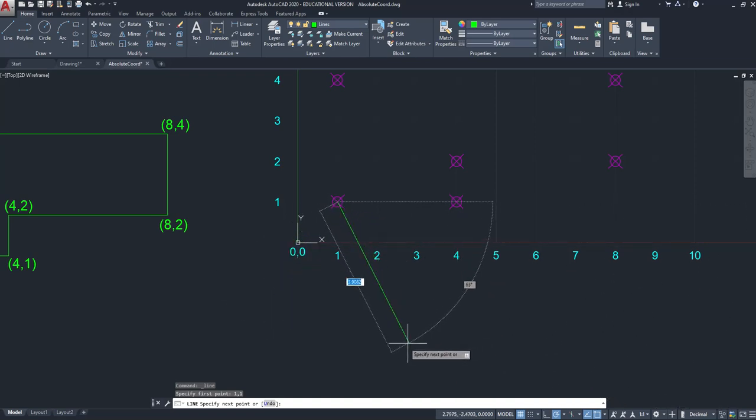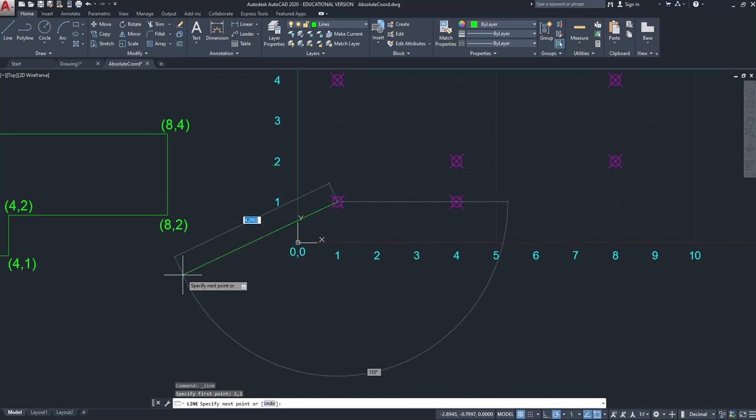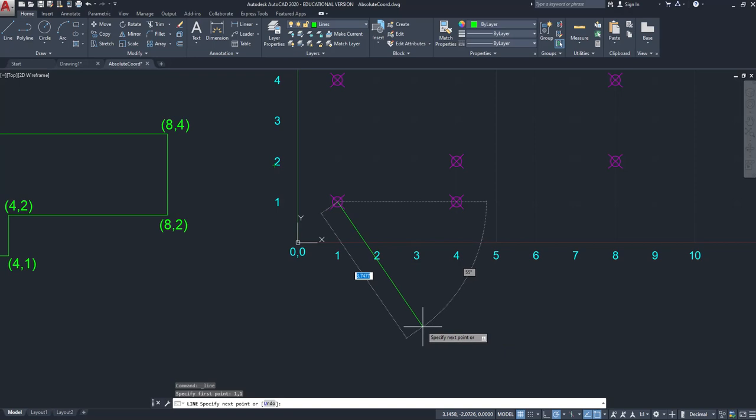Another thing that you're going to notice, you see all this stuff on the screen. This is called a dynamic input, right? And I may have said this in our previous class, but this dynamic input where all of this garbage is on the screen, it started happening maybe 8 years ago or so, and it just was an upheaval in the architecture community. Everybody just didn't know what to do with themselves because of this terrible stuff on the screen. So I'm going to have you guys turn it off for a minute, okay? I'm going to hit escape, right? To break a command, we hit escape.